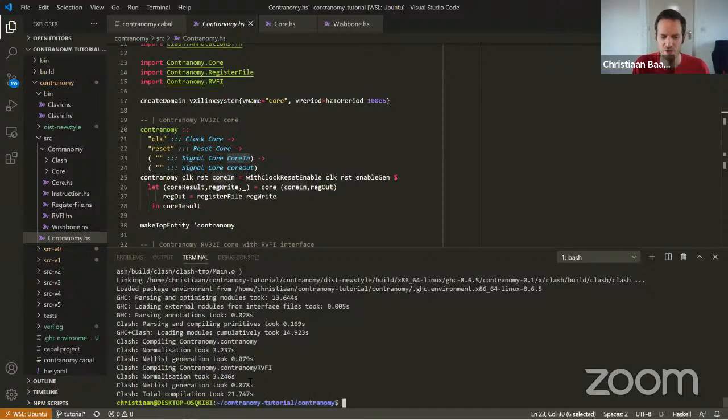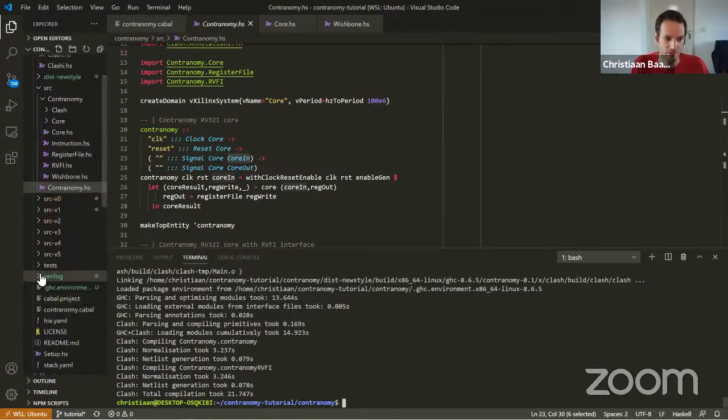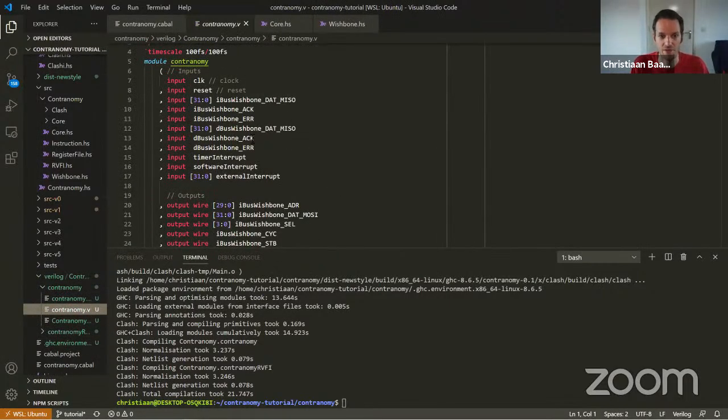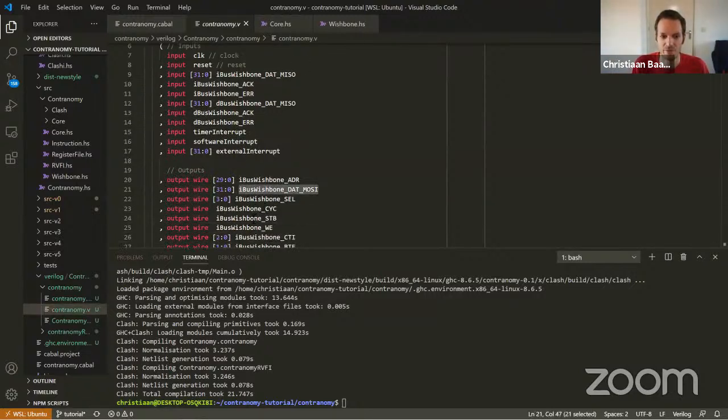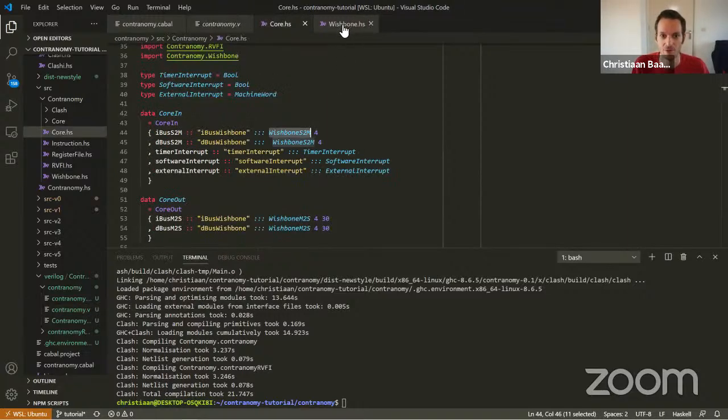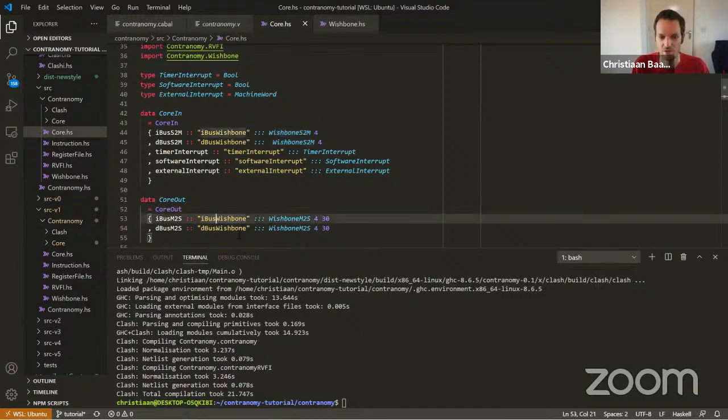It generates 2 versions of the core, one with the special output for the formal verification, and one that we'll use to integrate into the SoC builder, LiteX. So if we now look at the generated core, here we can see that we got all of these addresses as we specified them here, or nested, because here we said I. So it uses the nesting as well.